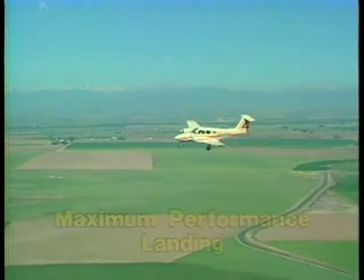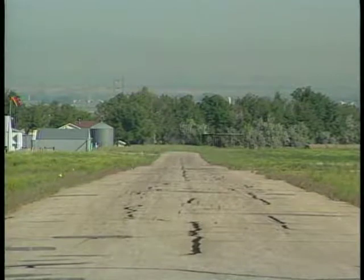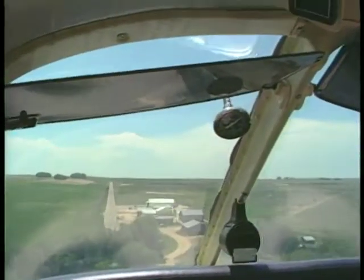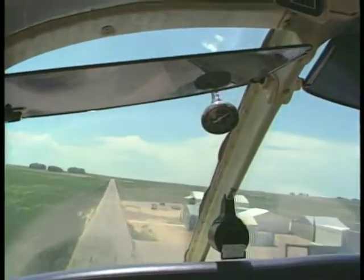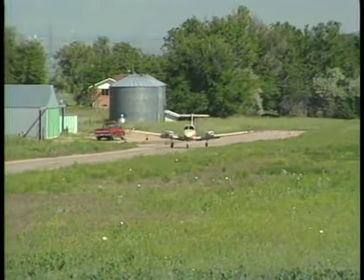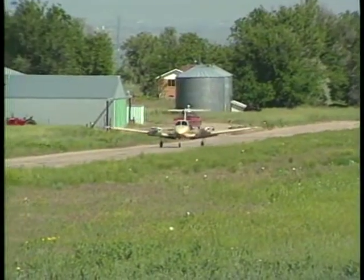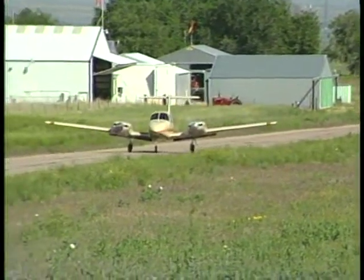The last type of landing we'll cover is a maximum performance landing. It is most often used to clear a 50-foot obstacle and land within the shortest possible distance. The final approach is flown at a constant glide angle with full flaps and a slightly steeper approach. The touchdown should be near the stall speed with little or no floating. Elevator back pressure improves braking action by putting more weight on the main wheels. If absolutely necessary, the flaps may be raised for maximum braking.